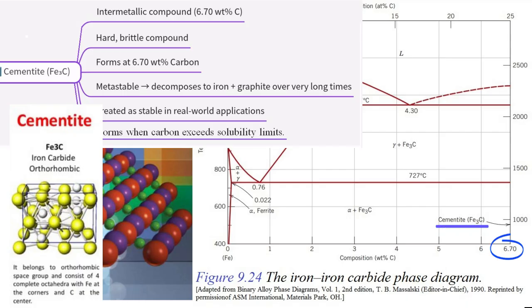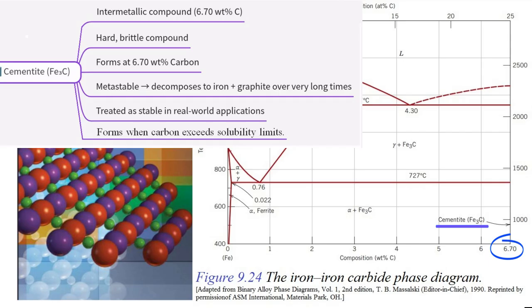Now, there's a slight technical point. Cementite is actually what we call metastable. Metastable, meaning? Meaning it's not the absolute lowest energy state under all conditions. Over geological timescales, or if you held it at high temperatures, say 650, 700 degrees C, for a very, very long time, it can eventually decompose into iron and pure carbon in the form of graphite. Graphite, like pencil lead. Essentially, yes.